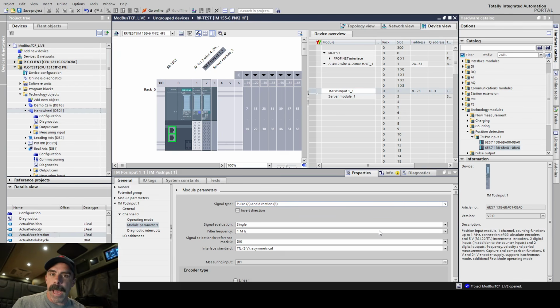Remember, I said an absolute encoder is always going to give you the position in some way. An SSI encoder has its own little industry standard protocol that it uses, and you have to have some module to interpret that data so it comes out as a position.